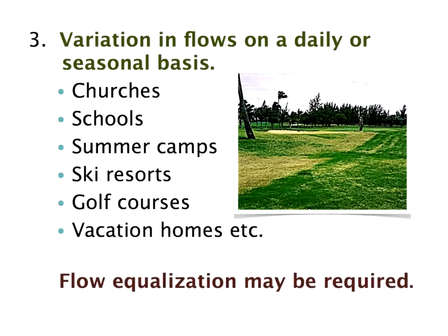I mean, obviously, churches get very heavy flows over Sundays or weddings or other events, schools, summer camps, ski resorts, golf courses, vacation homes. In many of these cases, you're going to need flow equalization. In many, many cases, flow equalization is actually a good idea, and on large systems, it's often very necessary. On a lot of single-family homes, it's usually not done because of cost.